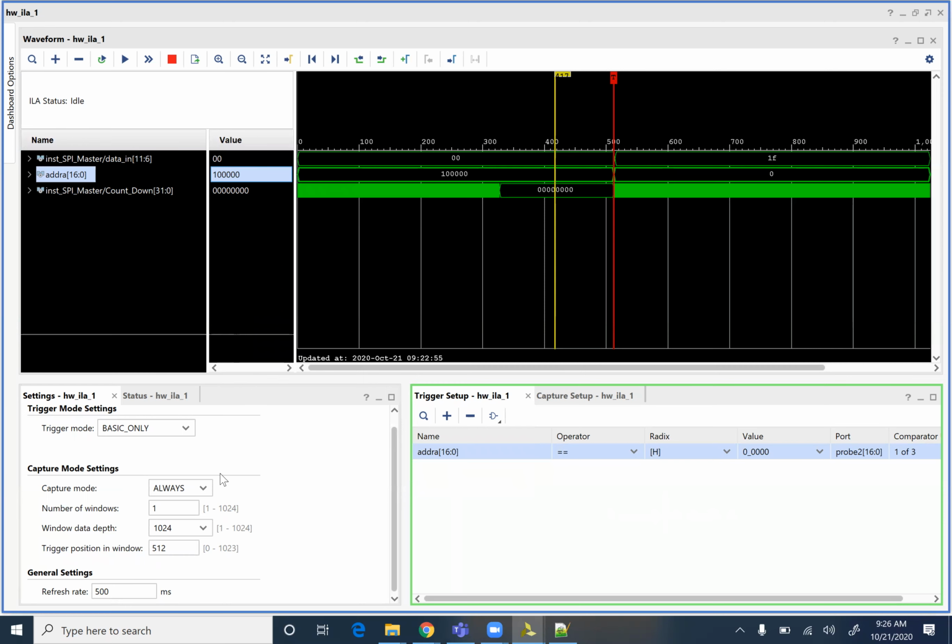So you'll set the clock low, set up the data that you want to clock in, and then raise it high. You're definitely going to want to start out by drawing a state diagram. If you don't draw a good state diagram, you're going to have a really hard time writing the code. And then you can always check off with me to make sure your state diagram is going to work, and I can point out where issues are.